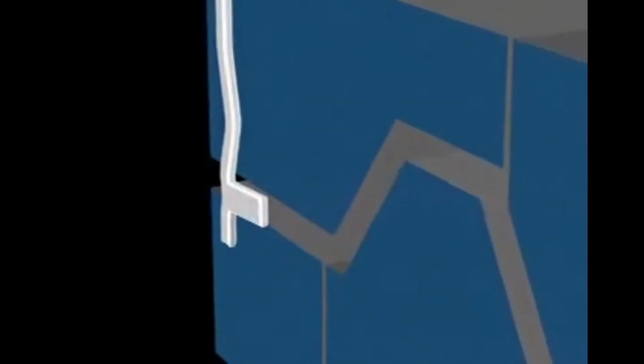On modern-day knitting machines, needles make millions of loops or stitches a day. Needles may need to be replaced due to wear, but they usually last up to 6 months, depending on construction, yarn type, fiber type, and speed. Next, let's take a look at what causes the needles to move up and down.